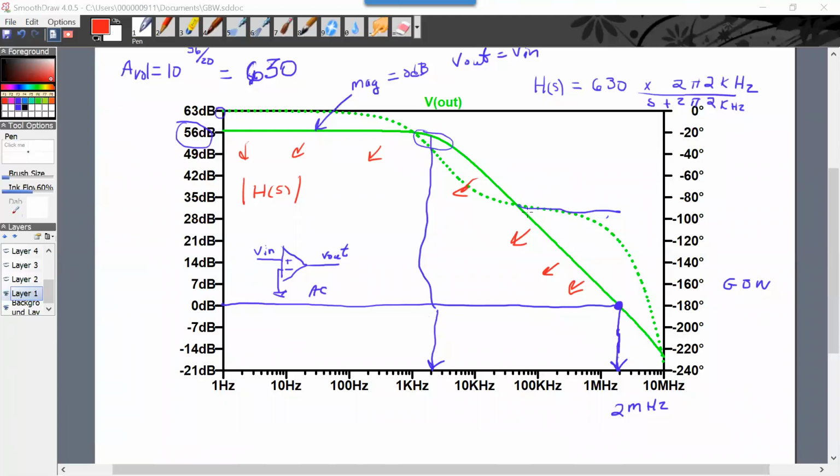What would I call this? I guess this whole topic is gain bandwidth, right? And I'm just trying to show you what the data sheet is, and this would be the open loop gain. So if I say, here's a Bode plot, tell me the open loop gain, and then either identify or what does the gain bandwidth mean? That's this spot. Call it gain bandwidth, AVOL, and we're doing it graphically on a Bode plot.